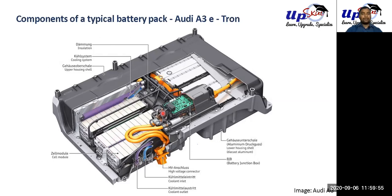This kind of design is not very suitable for intense applications. This is only for mild load, because it will heat up, and the cooling method doesn't seem very efficient. Also, it's very cost efficient, but it's not very functionally efficient in my opinion. But maybe they don't need high performance for this particular battery because it's going on a PHEV, or maybe a milder hybrid, so it only assists.